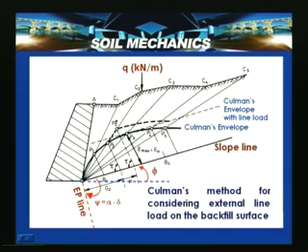So, this envelope is the envelope with line load, and this is the same envelope without any line load. Again, by drawing a line parallel to this and parallel to this, you will be able to get the PA, which is nothing but the active pressure thrust, which can be obtained graphically here by measuring Emax equal to EA equal to PA.